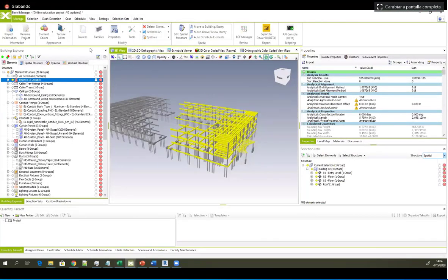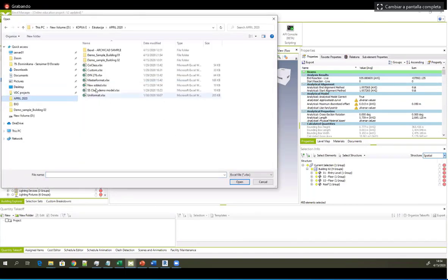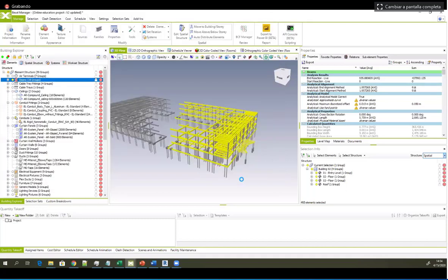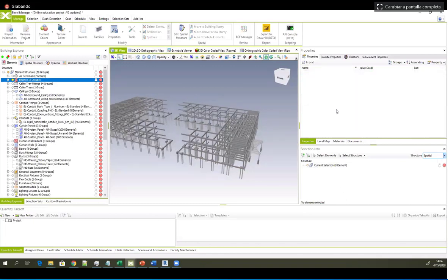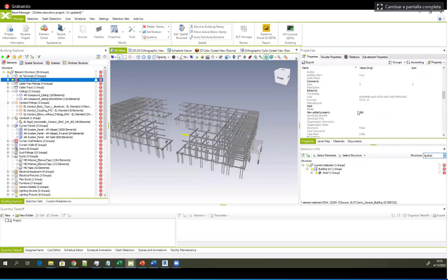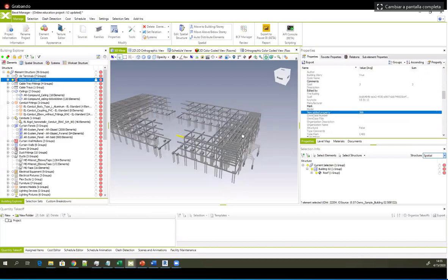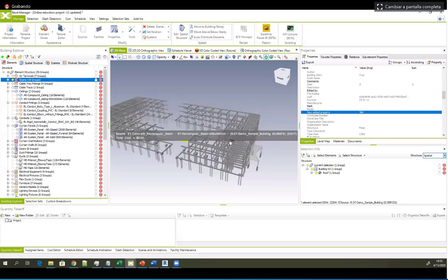So using the option import properties from the manage properties toolbar, I can import properties, and I'm going to use the same Excel spreadsheet to add these properties. So now we can check if these properties are added as we want it to. So new edit property now has changed value. And this is the way how you can use that for enhancing the quality and information within your BIM model.